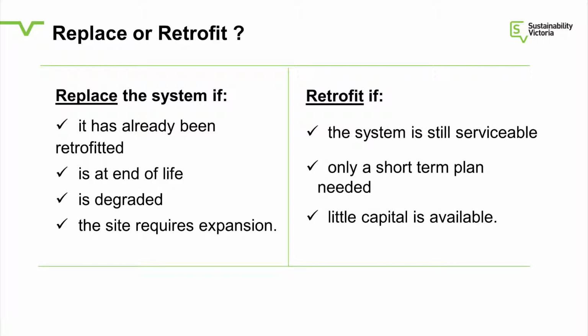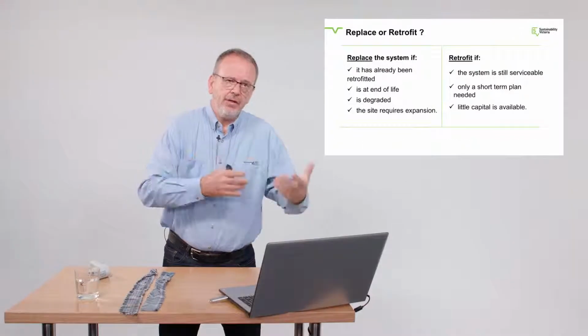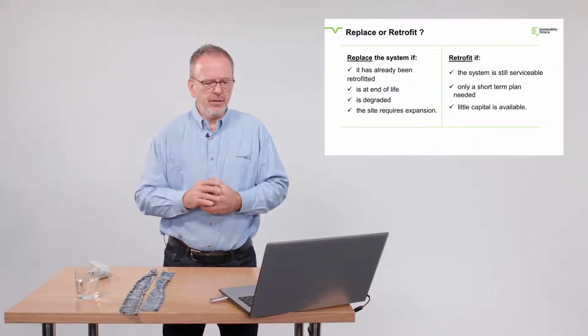That is, you've just invested a lot of money into it, the equipment is still sound. There is an argument to be made to retrofit those. There are some transitionary refrigerants available, like R448A, which could get you across the next 10, maybe 15 years, if you're lucky. Or if you just need a short-term plan. If you have a system which is on R22 and you just need to get over the next 3 years before you move to new premises, well, there's potentially a solution for that.